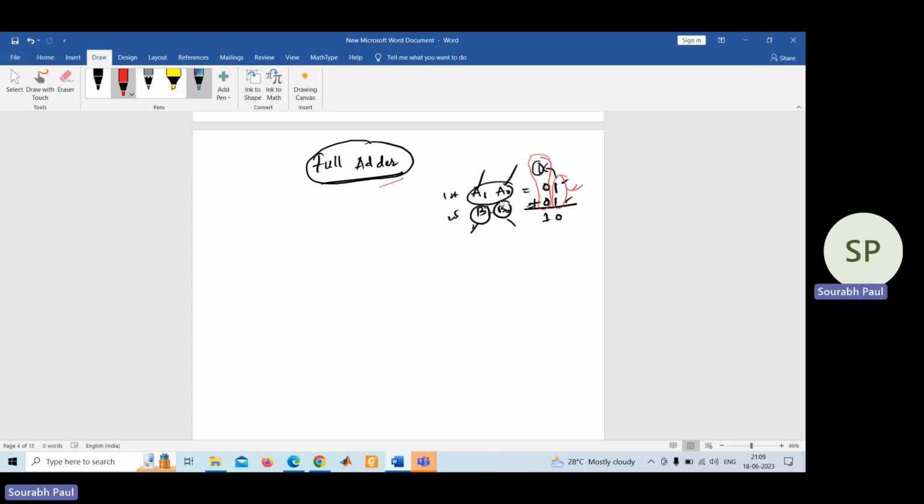So how can you say this clearly? What you are doing actually is adding two numbers with a carry digit. Is it yes or no? Yes, we are adding two numbers having a single bit with a carry digit. And this is the idea of a full adder, where you need to add two numbers, each having a single bit, with a carry bit.